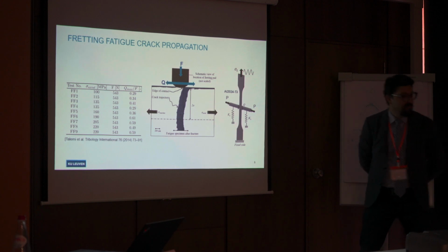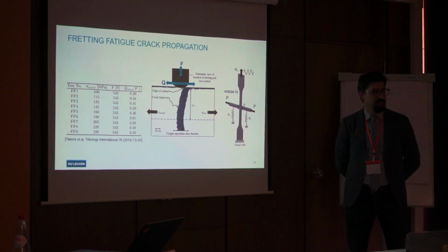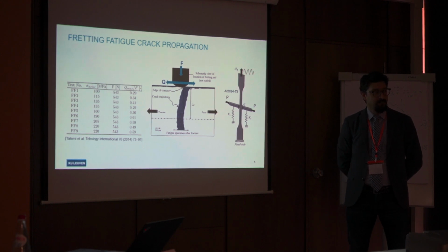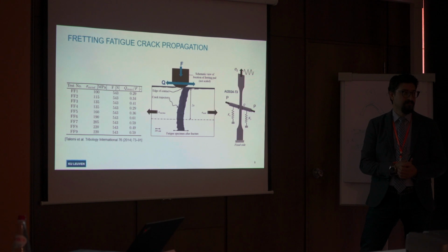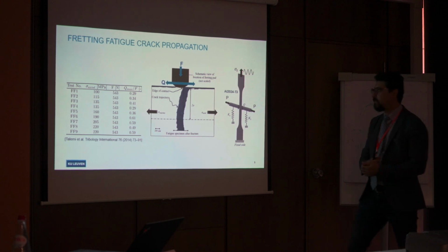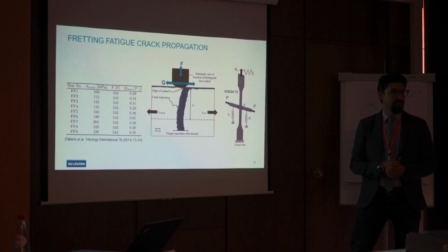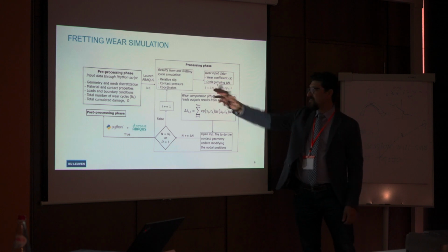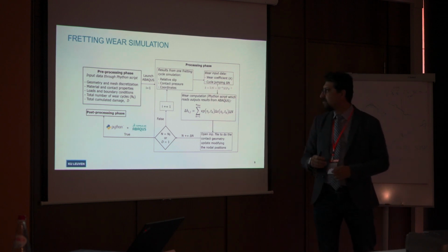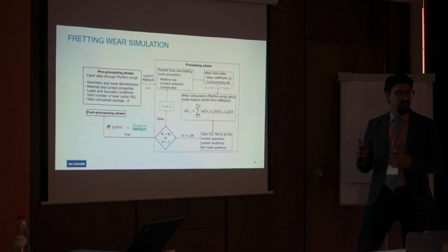Thank you for the presentation. Can you comment on the friction model? Your message is to please consider wear, because it has importance. How do you model the friction contact? As I said, we are using the Lagrange multiplier as the algorithm, and a coefficient of friction of 0.5. And what about the wear rate? The wear rate we took from the literature, 5.81 × 10⁻⁸.